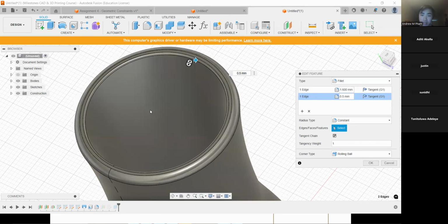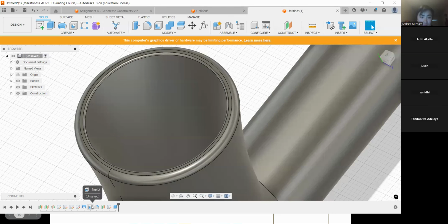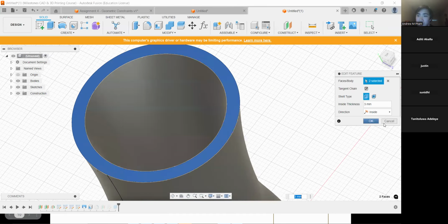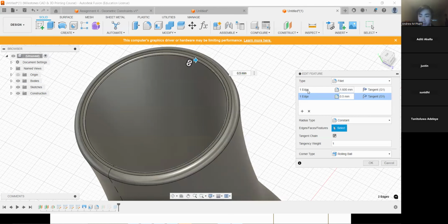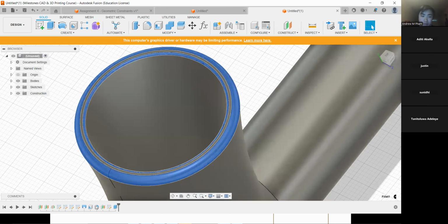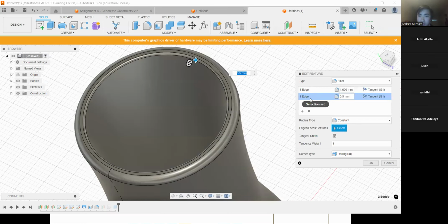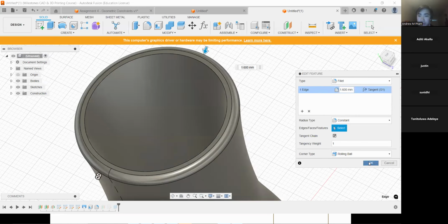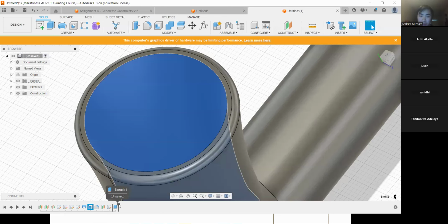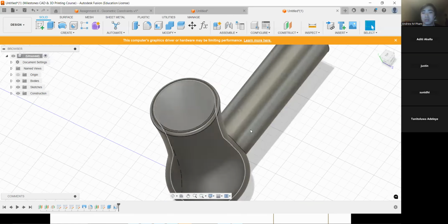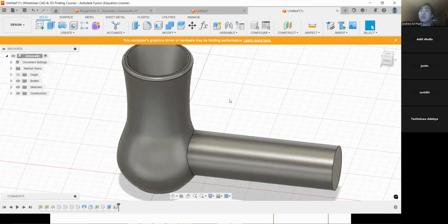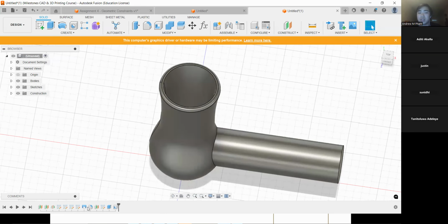Again, if I delete that fillet feature, it lets me. If I remove that and I try to push the shell forward, it will let me do it again. How do you hold and drag the shell? It's just a simple left click, just like holding down on most things. Again, if it's not dragging, it's probably because of a dependent feature like a fillet or something.